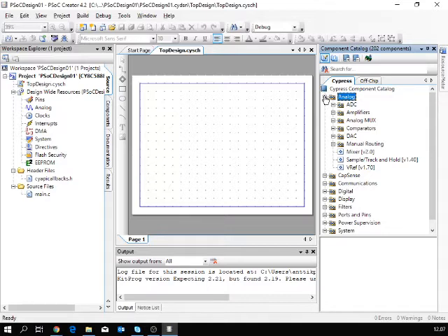If you find it impossible to route by this automation, then you can route the analog signals yourself. Good luck with that though. And so on. So it has different analog function building blocks. Oh yeah, sample and track and hold. That kind of thing also, that you would use with the successive approximation type of analog to digital converters.